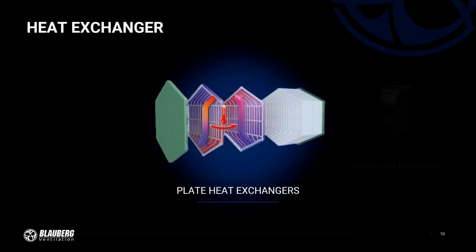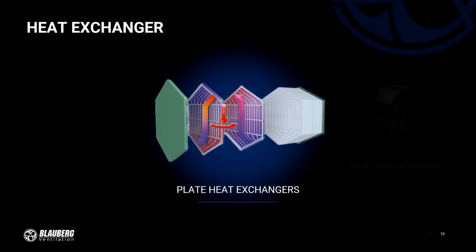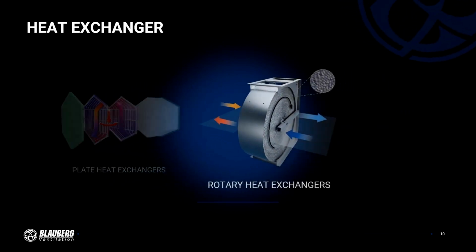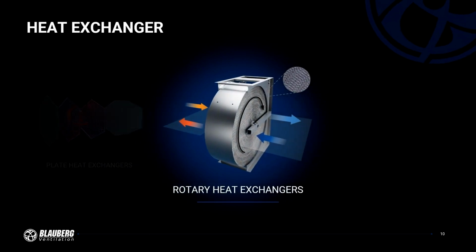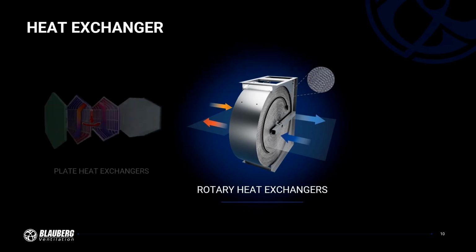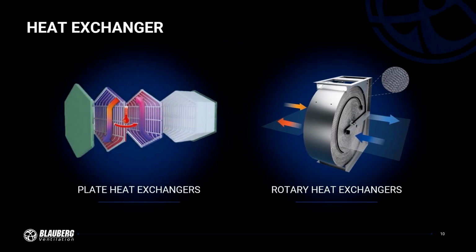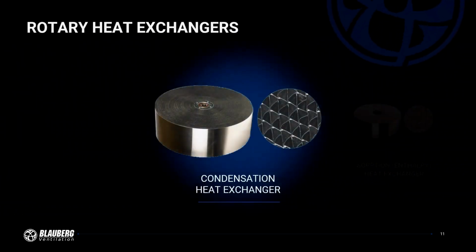Unlike recuperators, rotary regenerators transfer energy by rotating a heat-absorbing material that alternately comes into contact with supply and exhaust airflows. Since the surface of the heat exchanger is alternately exposed to warm and cold airflows, condensation does not remain in the rotor matrix. As a result, rotary regenerators do not require freeze protection. Traditionally, units with rotary regenerators are used in cold climates, as they are better protected against freezing.